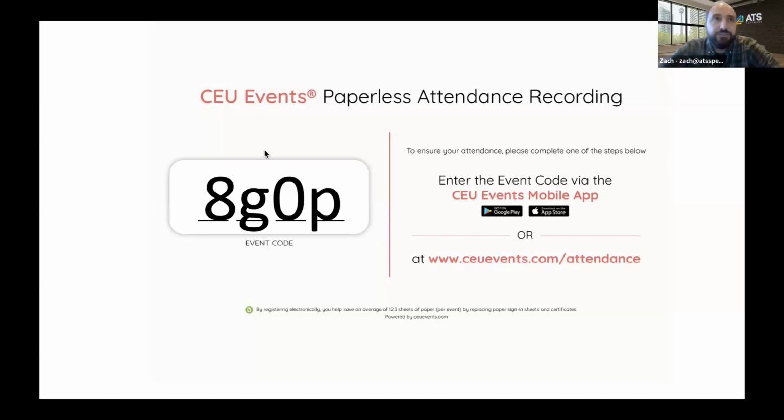Well, and beyond the shower head itself, my internet kind of glitched out, so I may have missed this if you talked about it. My understanding is that there are valve considerations as well. It's kind of like how with the thermostatic and pressure balancing, there's a higher flow rate. That's because you need a certain amount of flow going through the valve in order for it to properly adjust the temperature and limit the temperature. Right. It's true as well for the pressure balancing on its own. There is a minimum flow rate that needs to go through that valve before you start getting the hot-cold sandwich that was prevalent before these low flow valves became available.